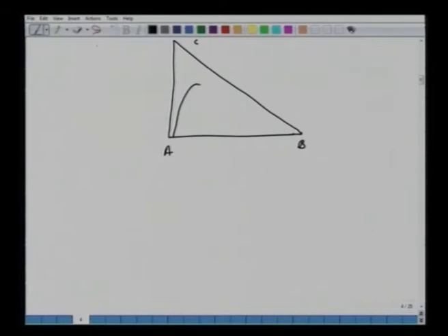If we keep on increasing the amount of solvent, then E1 extract will move in this direction. So S goes in this direction, E will go in this direction, and the line connecting this E to F, which gives us del R, moves in this direction. Till we keep on further increasing, this line E, extract, F and del R will become parallel to this line.